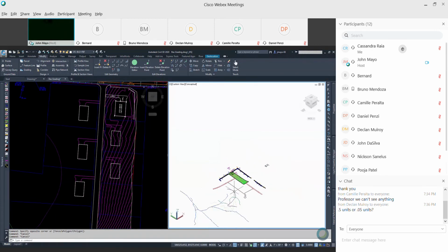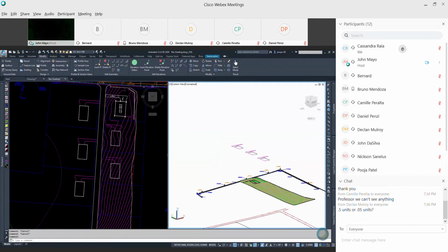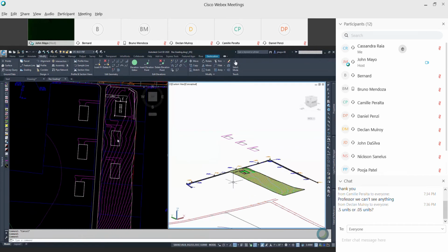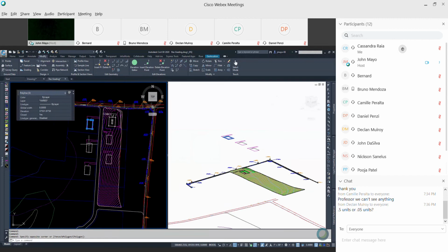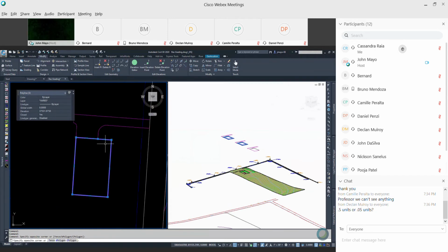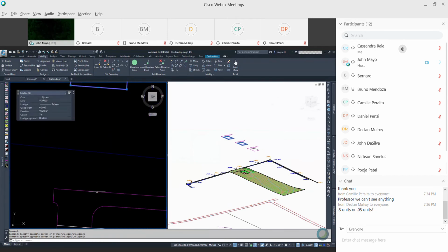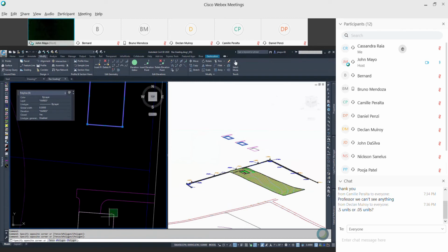And you want to do that all as 2D polylines because it's a lot easier to do than doing it when it's feature lines. Here's another little trick too. If these are all polylines that are beginning at elevation 0, and let's start with that.